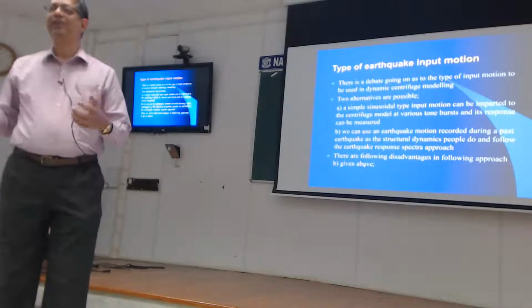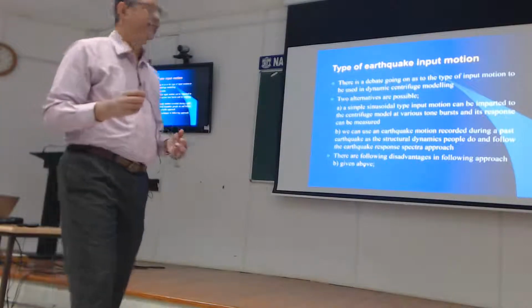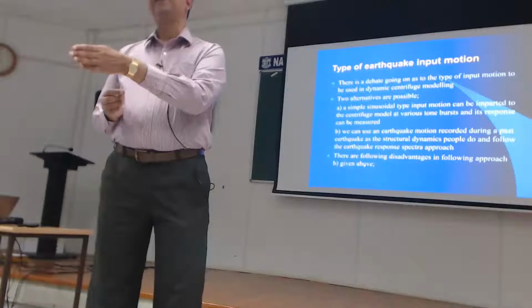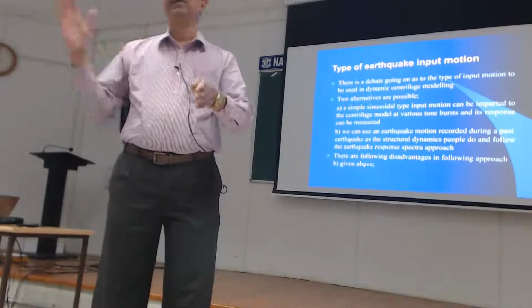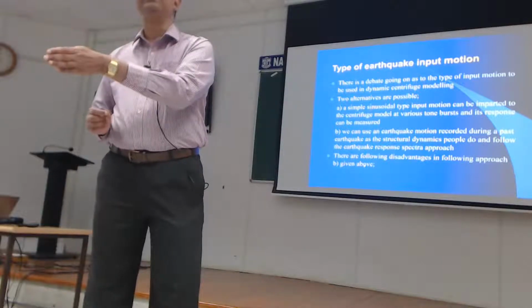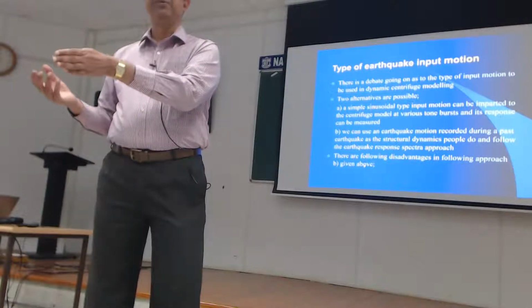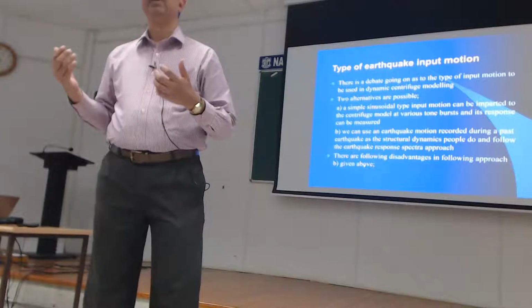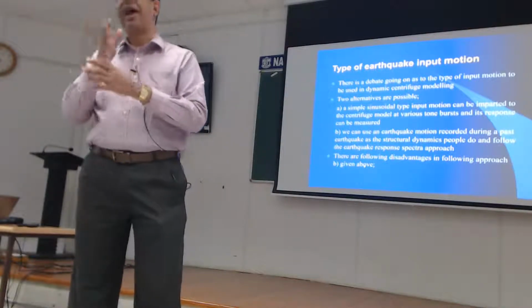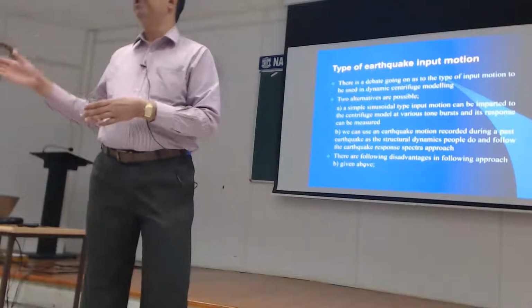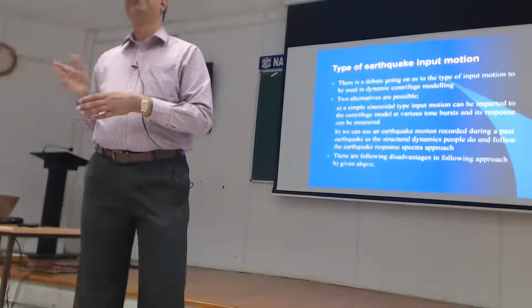You're aware of that, I hope, eigenmodes and eigenfrequencies. If you deliver the energy at half the eigenfrequency, it does one thing. If you deliver the same energy at exactly its, say, first mode eigenfrequency, it will respond wildly, right? Because it's resonating. So you can track the response of the structure by applying a series of sinusoidal waves at different frequencies.